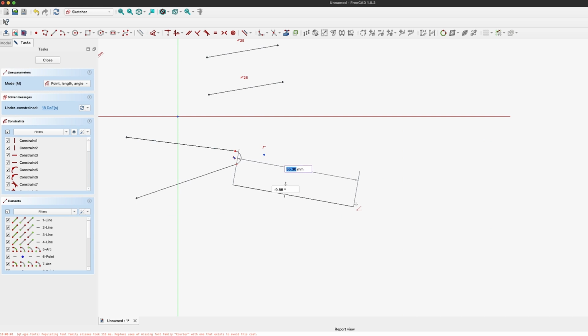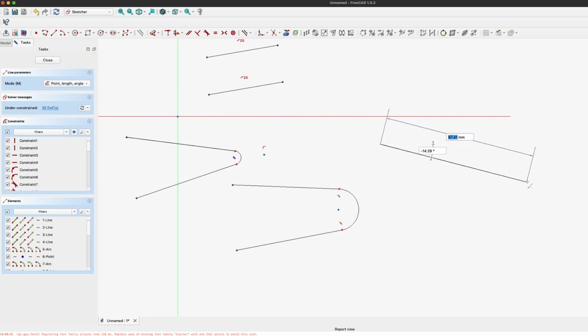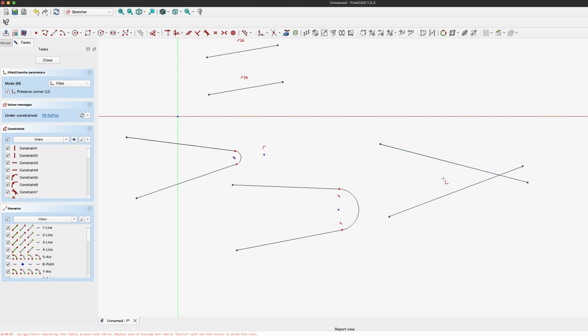And it's not like you need that particular intersection. Even if they are as of now not intersecting, and you still apply a fillet here, you can see the fillet is automatically created. But how about when the lines extend further from that intersection? For example, in this case, let's again go to fillet and apply it. The size you choose will remain along with the fillet, and the remaining part will get trimmed.